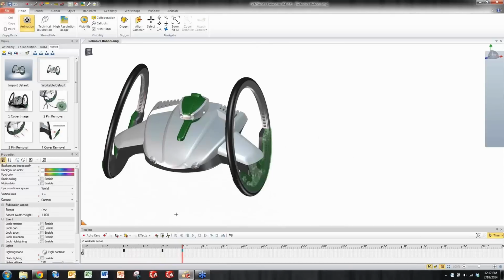So creating keys, the very first one we're looking at here, it's grayed out now because I have no components selected, but I have set location key. This key always controls where a component is in space. So that's what this key is. We need to set this before we move the component and after we move the component. So we set 2 location keys, one for time A, one for time B, and that's really all there is to it.